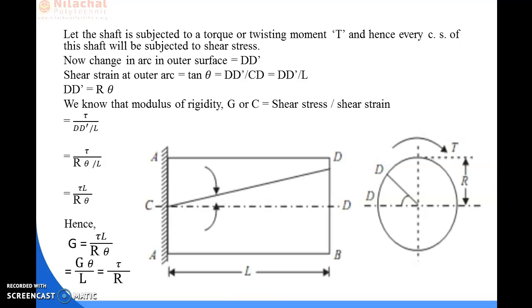So in this part we have to consider the angular deformation for the twisting moment in the shaft section. As you can see, this is the fixed support for the shaft, and this is the neutral axis along the length of the shaft. Then due to the twisting moment, that is the torque, this axis in the longitudinal direction is deformed to here.